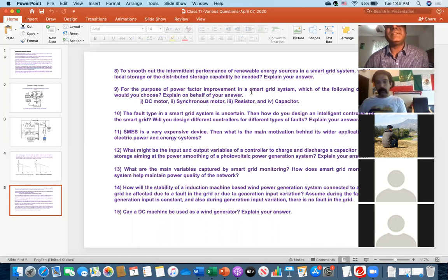So, the same thing, the synchronous motor under a certain condition. What's the condition? When it is in overexcited mode, when the current leads voltage by 90 degree, and the other condition, there is almost no mechanical load connected. You are just running a motor, similar to the flywheel storage system.